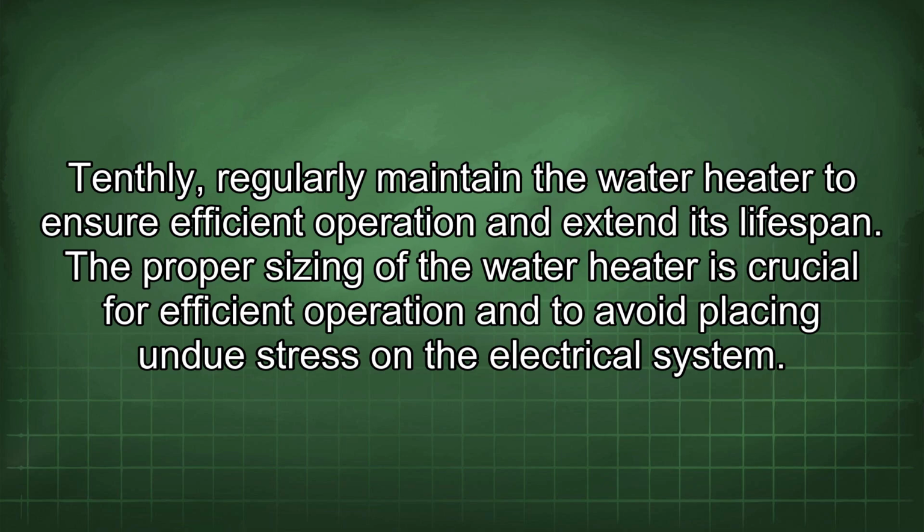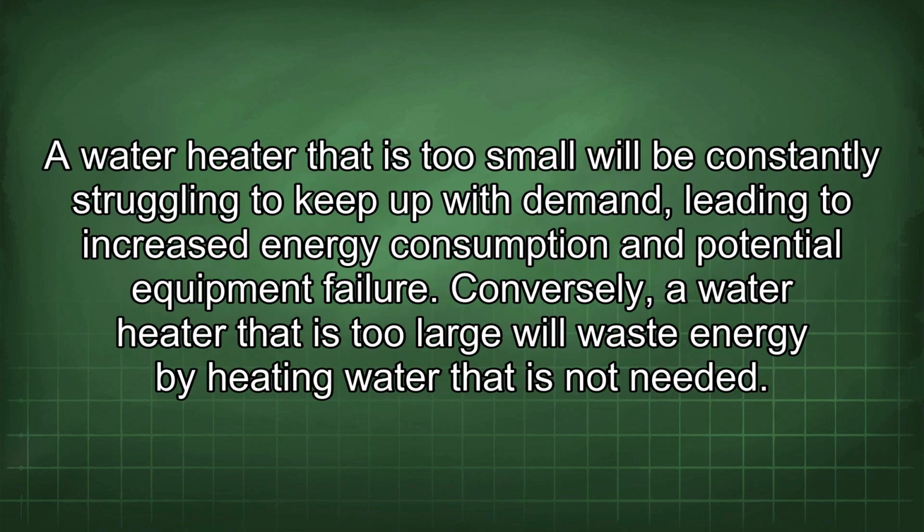The proper sizing of the water heater is crucial for efficient operation and to avoid placing undue stress on the electrical system. A water heater that is too small will be constantly struggling to keep up with demand, leading to increased energy consumption and potential equipment failure. Conversely, a water heater that is too large will waste energy by heating water that is not needed.